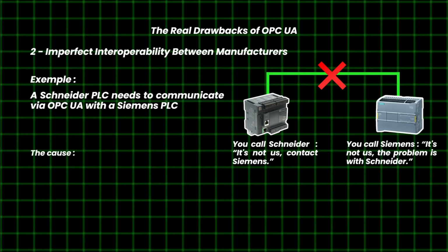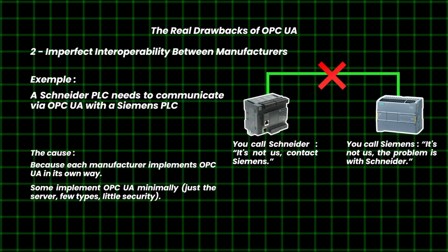And the cause is that each manufacturer implements OPC UA in its own way. Some implement OPC UA minimally, just the server, few tabs, little security. OPC UA profiles are not always the same between manufacturers.